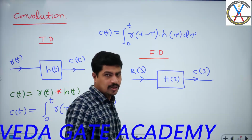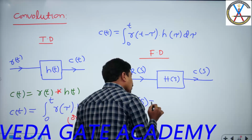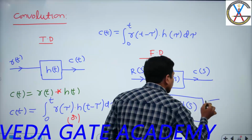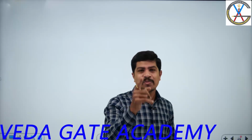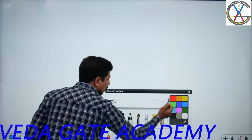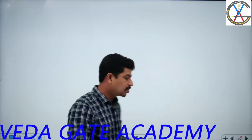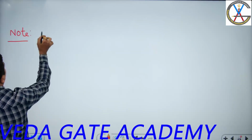When you apply the Laplace transform, r of t becomes R of s, h of t becomes H of s, c of t becomes C of s. Then C of s is equal to R of s into H of s. This is the greatest advantage of the S domain. Note this point: difficult convolution in the time domain becomes simple multiplication in the S domain. It's very, very important. You might have a doubt about the proof, but you will learn it along with the proof in signals and systems. All of you must remember this note point: convolution test.